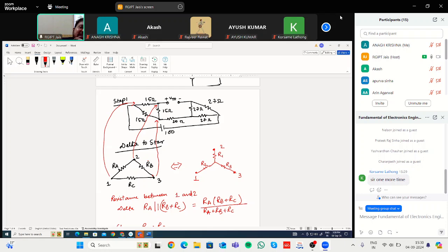let us say in this circuit, we are trying to solve this circuit. Here we can clearly see that this is a delta configuration. If you see only this part, this is a delta configuration. If you see this part, this is a delta configuration. Definitely, you can consider this as a mesh, but for that, you will require two extra equations. Multiple simultaneous equations are difficult to solve in a time-limited manner. So it's better to see if you convert into star, whether things become easier or not.